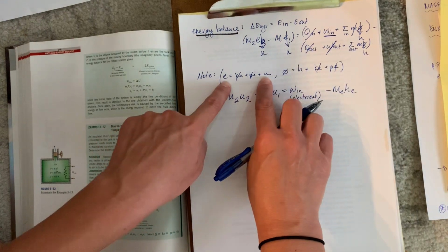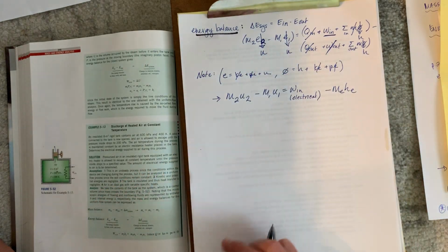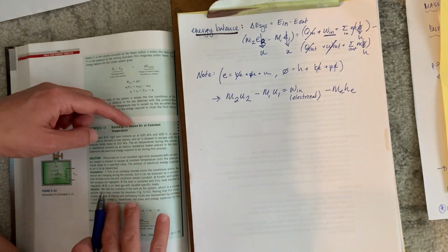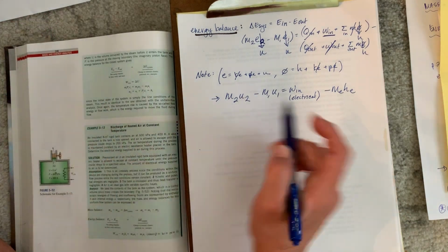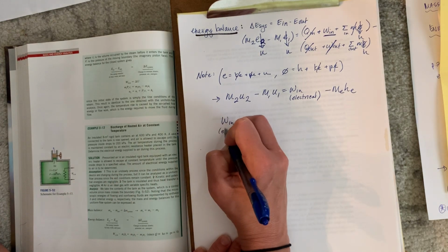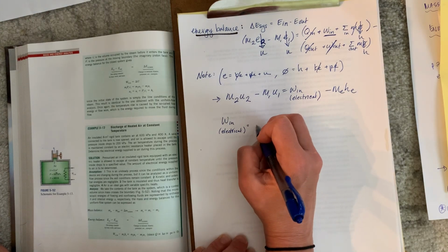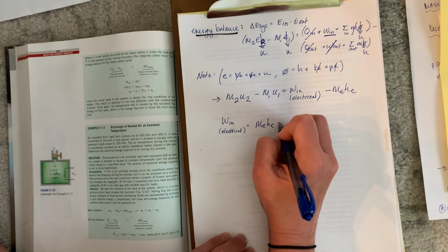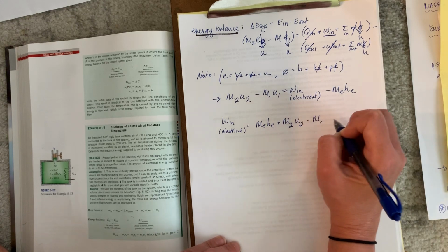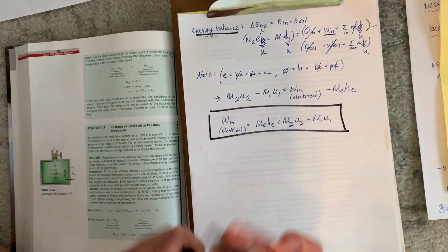So as a reminder, we're using internal energy and enthalpy in terms of specific energy and flow energy here and reducing down the equation. So the problem statement is asking for us to determine the electrical energy supplied. So we are trying to isolate electrical energy here. Our equation becomes our work in, which is our electrical work done by the heater to keep the air at a certain temperature, is going to be equal to mass exiting, enthalpy exiting, plus mass at the exit, internal energy at the exit, minus mass at the inlet, internal energy at the inlet. So this is our energy equation for the problem.